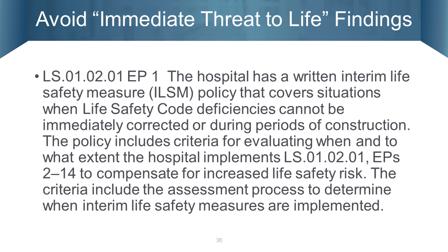Okay, immediate threat to life. If you have a life safety deficiency and you've not completed an interim life safety measure, that will take you to immediate threat very quickly. So it's something that when you go through, even when you do your fire door inspection, if you're finding problems with fire doors, I would do an ILSM covering those items. And you might want to group those so that if you're finding holes in the door frame, that's minimal concern in a fire situation. I would think you could probably go through, lump those all together and do the ILSM, but then say that no further measures are required other than to repair it.